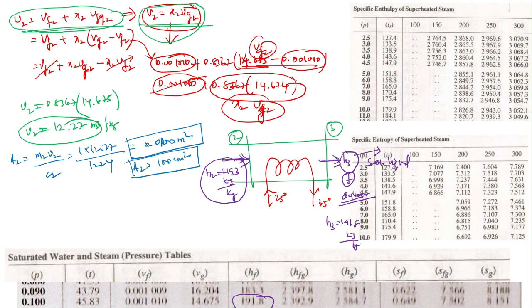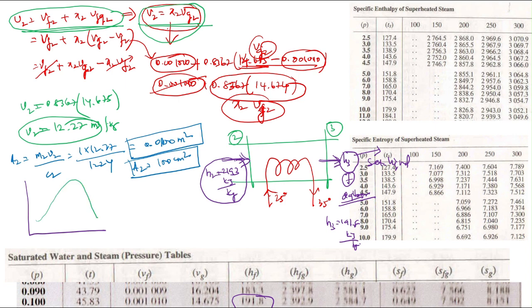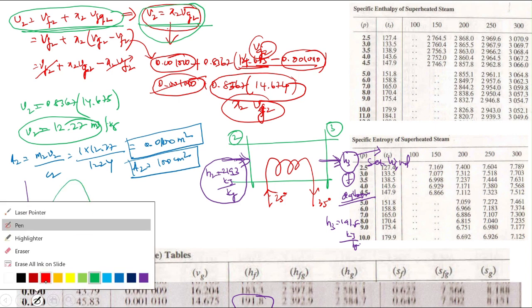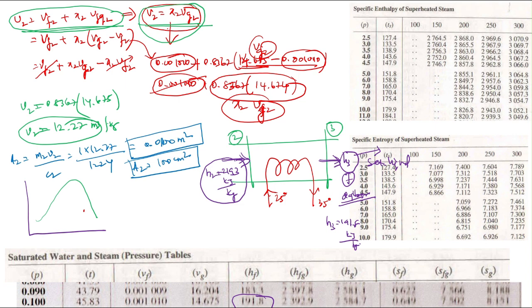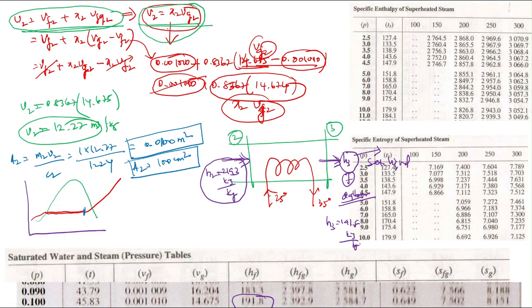Okay, here in the diagram it may be represented in a PV curve. Normally the condition at 2 is wet steam. Here it is cooled at constant pressure, say 1 bar. This is a constant pressure line. So it is cooled at constant pressure, from point number 2, until it reaches the saturated condition. Saturated means F, so we go to F.